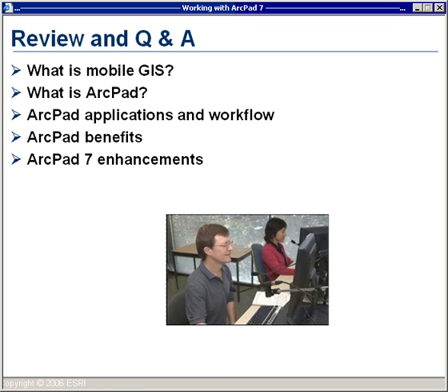The next question comes from Matt in Medina, who asks, I noticed you have an aerial photograph in your example. Is there a size limitation to how large the photo can be, either file size or dimensions, when extracting the data from ArcGIS Desktop? Yes, there is a file size limitation, and this limitation is approximately 17 megabytes for the image that is extracted from the screen view.